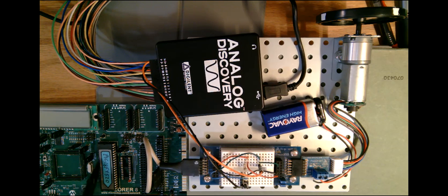So here we can see the actual PIC-18F4520 chip with all its 40 pins on it. Those pins are brought over here on the side, and if you could zoom in and read enough, you can see port C pin 1, port C pin 2, power and ground, which are then connected out this umbilical to this little mini breadboard. In this breadboard, I've got a push button switch with an actual pull-up resistor. See the little striped pull-up resistor here? There's my pull-up resistor hooked to red, which is 5 volts, and then that is being read via the blue wire back into the processor, port C pin 1.